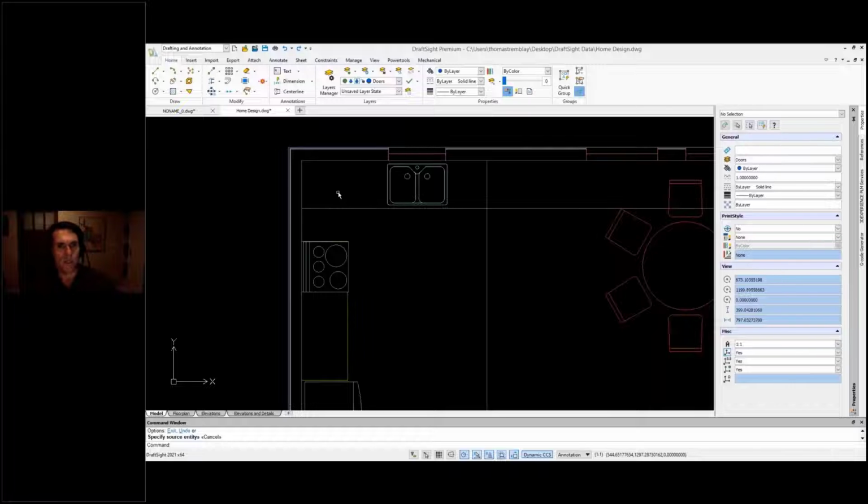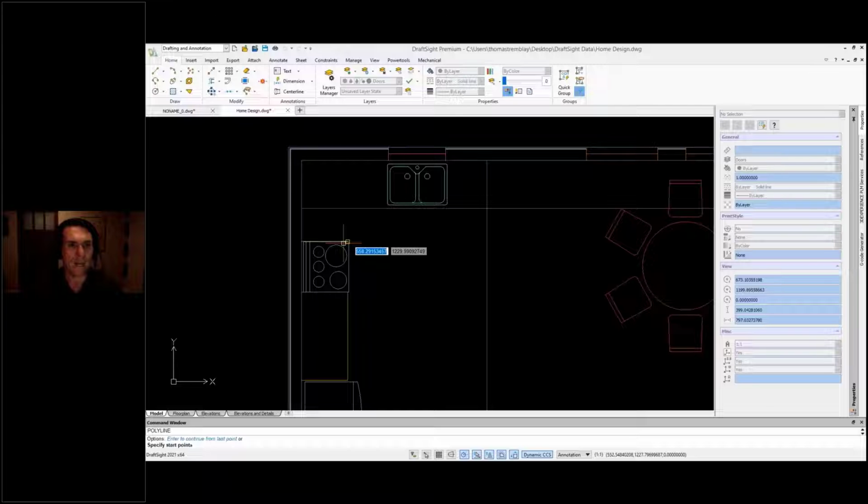The next thing I want to do is create a polyline. So what's a polyline called in DraftSight? Well, I'm used to typing PL for a keyboard alias, and sure enough, that's polyline, and it's called polyline. So let's create our polyline. And as I move around, I'll continue to use the entity snaps that I'm used to, how they work with perpendicularity and intersection. Here, I have my ability to put in distance and angle using tab, just like I'm used to, and just keep working in the fashion that I have been for years. I'll move this up, drop that in place.